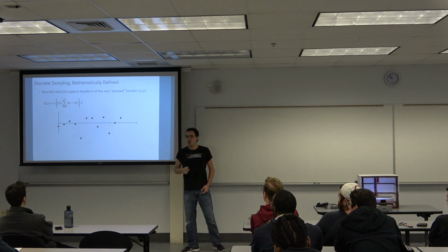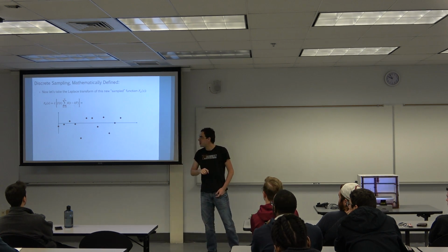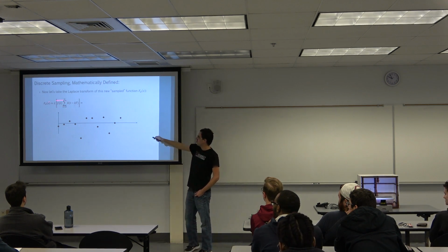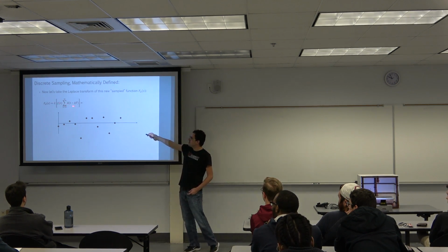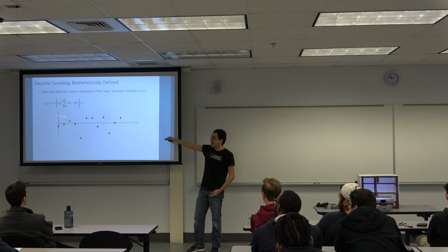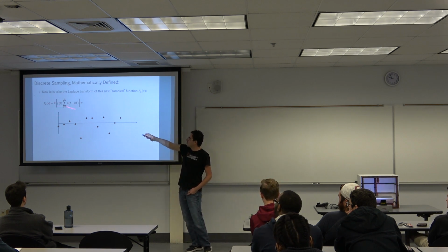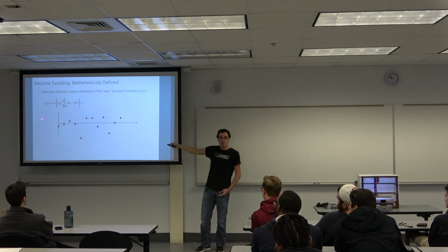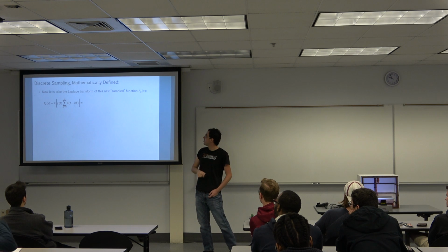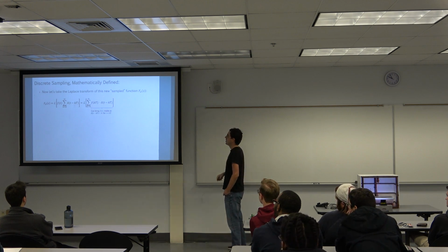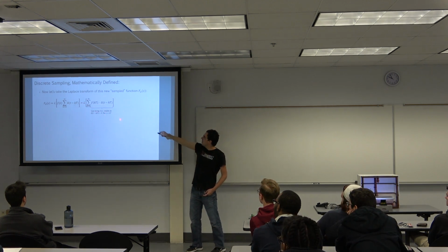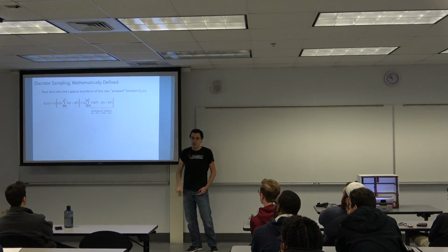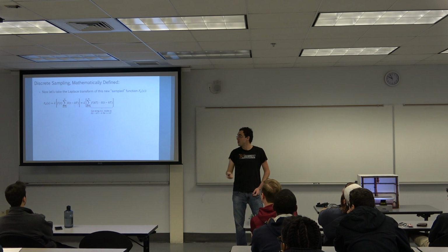And there's a little trick before we take the Laplace transform, which is realizing that after multiplying this, it doesn't matter if the function is in the analog domain or if it's already in the sample domain, because after multiplying these two together, the function is not going to be defined between the samples. So this means that I can just replace t in the continuous time by kT, which is the discrete time, k capital T.